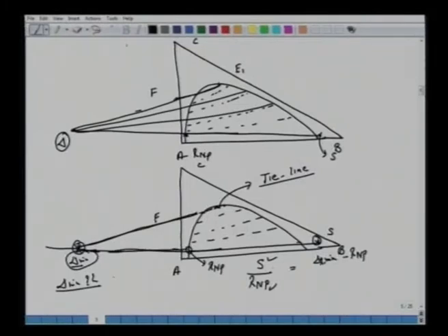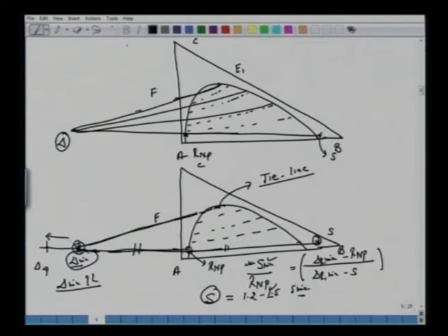All right. Now, if we choose any amount of solvent greater than S min, as you recall from the previous discussion, the operating curve will move further away. And if it goes to that extent that the del operating point has come to the right hand side, then we can also have the operating line right here. In this case, all the operating lines will originate from here, and in no way will any of these operating lines coincide with any of these tie lines. Now there is one more important thing here, that there is a possibility that some of the tie lines underneath this first tie line, which crosses through F, can give a del min larger than what we are getting right now.